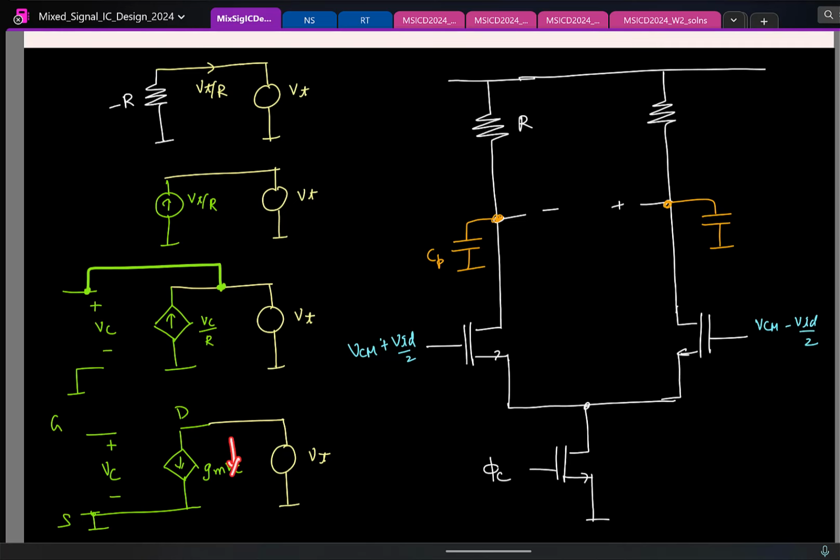So here I cannot simply go and connect it, right? Then I will be drawing out current. But if I were to pump in current like before, what should this voltage be connected to? If I connect it to VT, I will be drawing current in this direction. If I connect this to minus VT, then the looking in resistance is what? Minus 1 by GM. If I connect it to minus VT, the current drawn is minus GM times VT. Apply a voltage V, current is minus GM times V. Ohm's law tells you the resistance is minus 1 by GM.